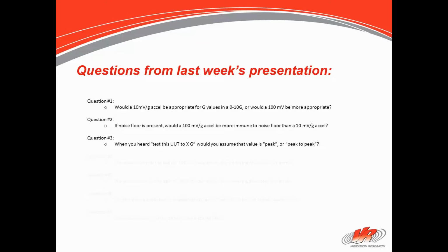And I have to mention one other slight deviation in sine that you have to understand. First of all, when you talk of displacement in sine, then suddenly it changes to peak to peak. So we talk about a 1-inch shaker. That means it'll produce a 1/2 inch displacement up and a 1/2 inch displacement down. So if we say we're running a 10G sine test and it's 1 inch, down at lower frequencies, you're going to hit the frequency where 10 G's produces 1 inch. Well, that's 10 G's only in the positive, but it's a 1/2 inch up and a 1/2 inch down. They talk that way because shakers are always rated in inches of displacement total up and down. So I think it's just a way to make sure you're not ordering up a test that you can't run on your shaker.